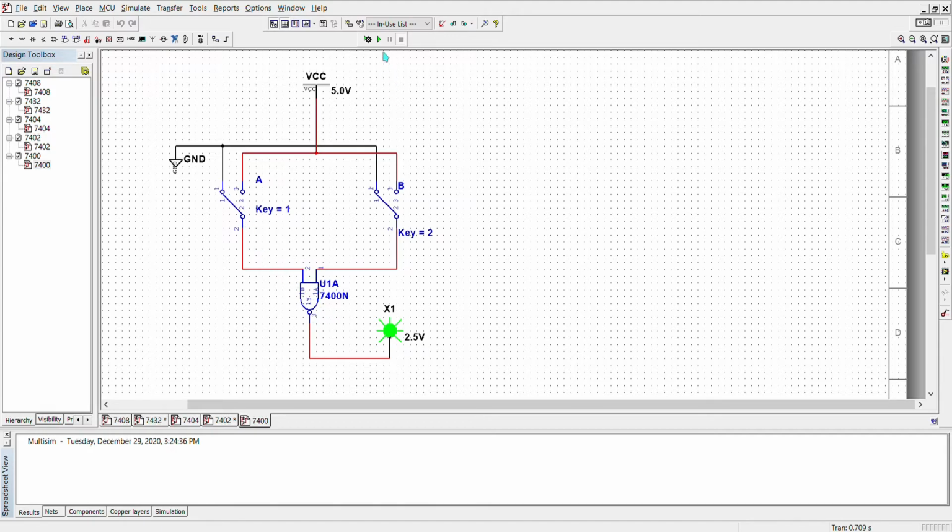By referring to the lab sheet, firstly, they need the input of A to be 0 and B to be 0. We will get the output 1. Then we will set the input B to 1 and the input of A 0, we will get the output 1. Next, we set the input of A to 1, the B 0, we will get the output also 1. And lastly, we set both inputs A and B to 1, we will get the output 0.